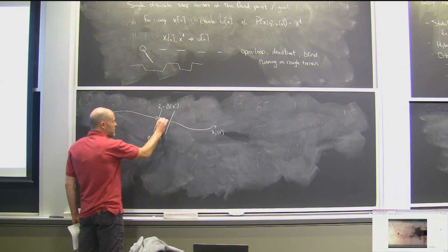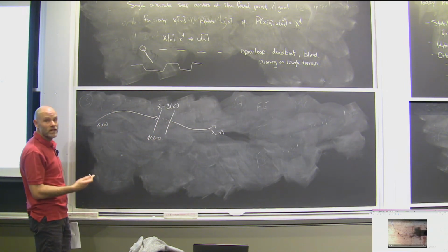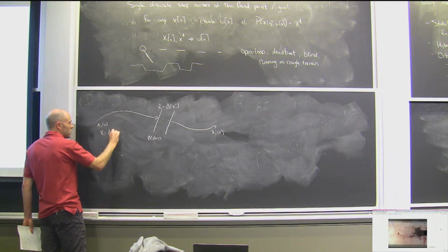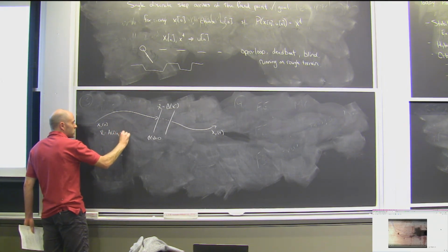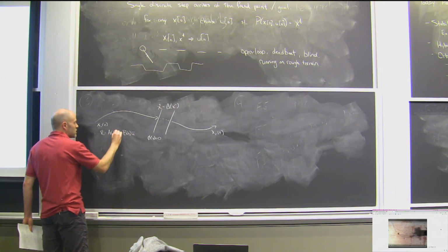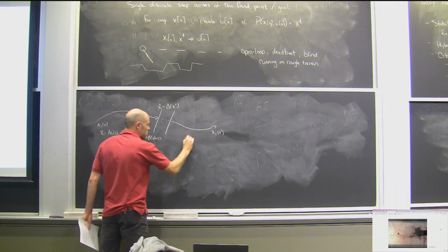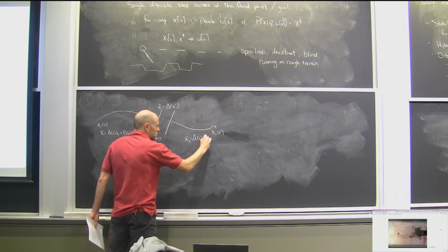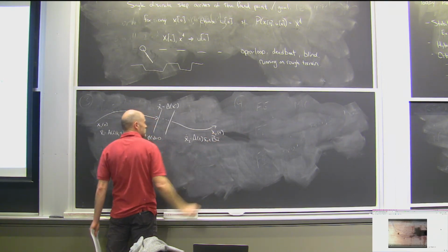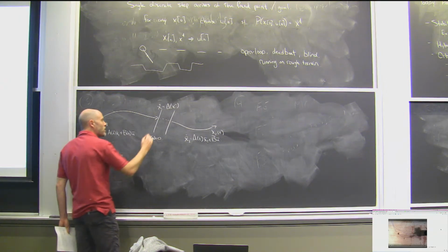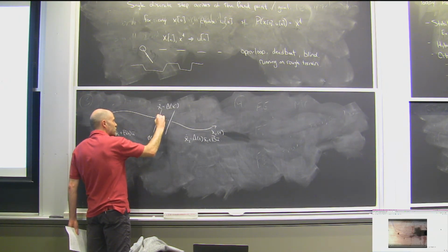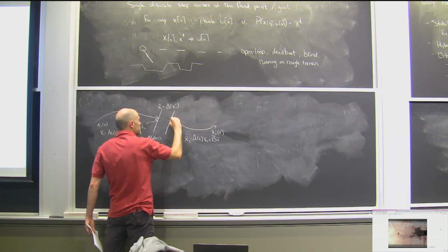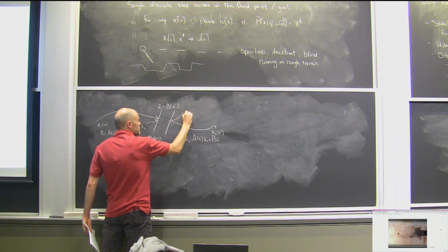But it turns out that the thing you kind of hope would be true is true: if I were to approximate this with a time-varying linearization, and this one also with a time-varying linearization, and let me call this moment of collision on the nominal trajectory my time of collision, TC, and the moment right after, I'll call this TC minus, and this is TC plus. Those are instantaneous collisions, right?